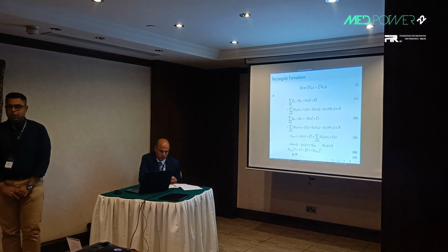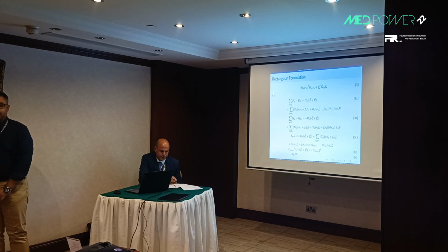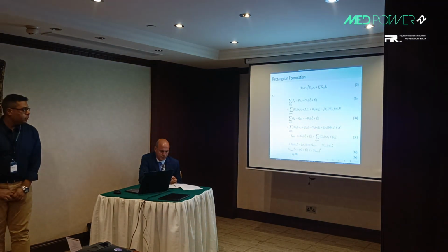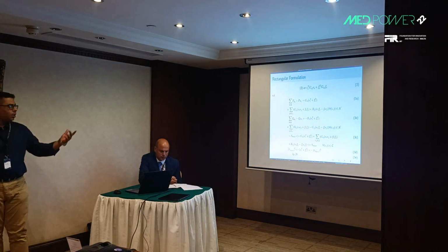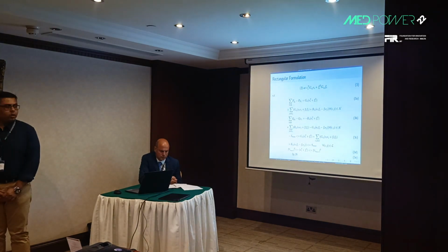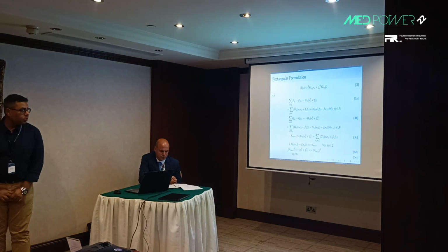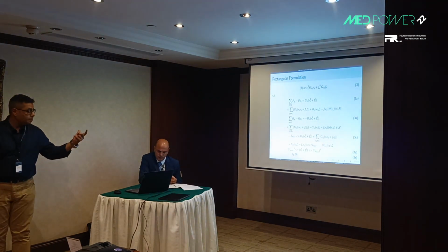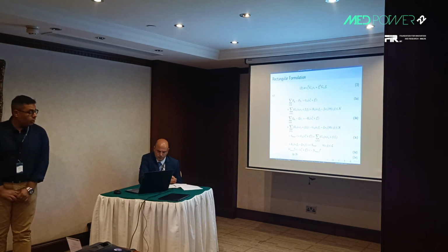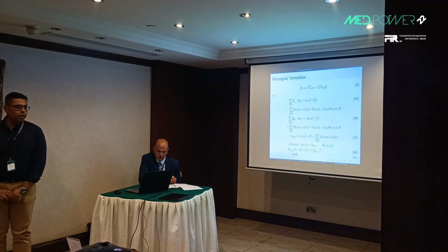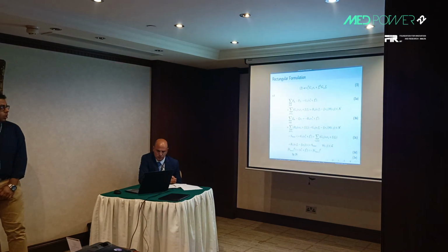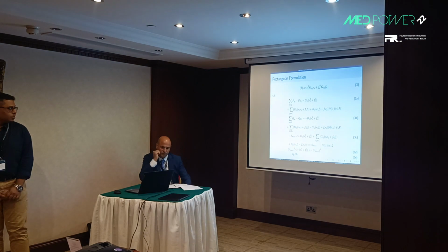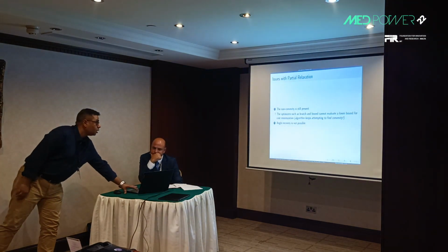So this is the partially relaxed OPF. We lift the terms to the rectangular levels. When we lift the terms to rectangular levels, one good thing is that the polynomial equations are now gone. The sine and cosine terms are gone, so it is partially relaxed. But at the same time, if you see equation 3D, the non-convexity is still retained.